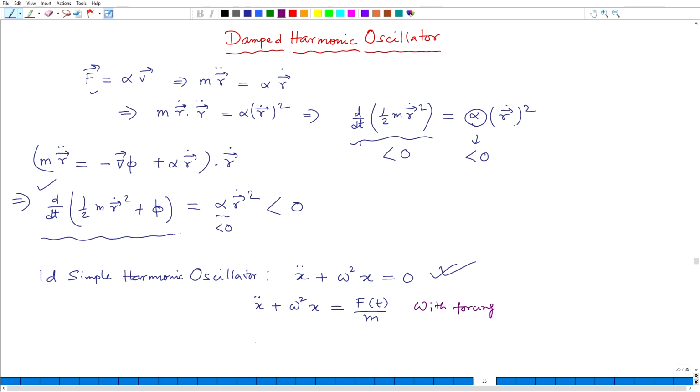and finally, if you want a drag force, then what you can do, this times some plus omega square x. Okay. I am now just considering no forcing which can pump energy, but some dissipative effect. So, I can write with some minus 2 lambda x dot. Okay. This is a forcing whose coefficient, lambda, I am just considering to be greater than 0 here, and this minus is just to ensure the dissipation of energy, and x dot is the velocity. So, that I can write.